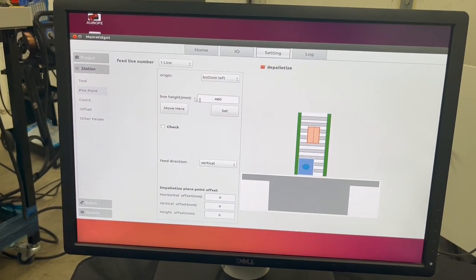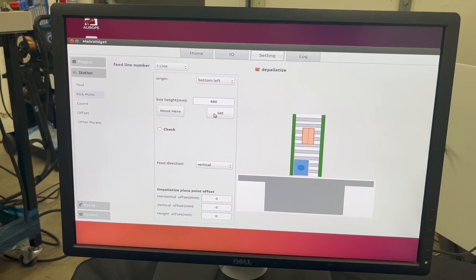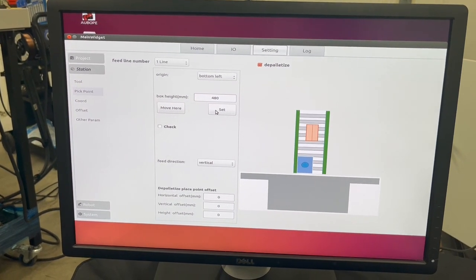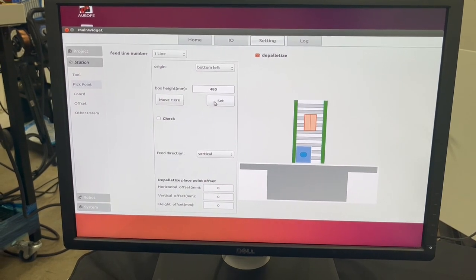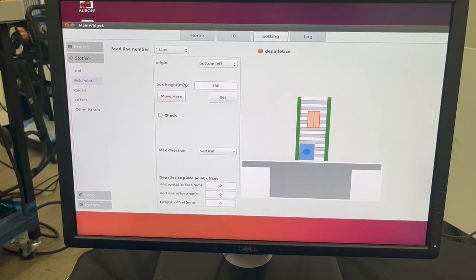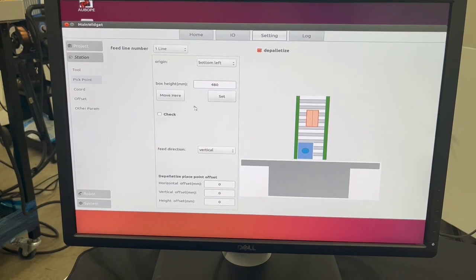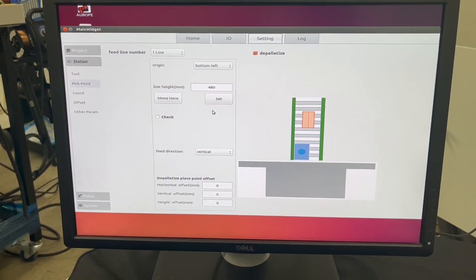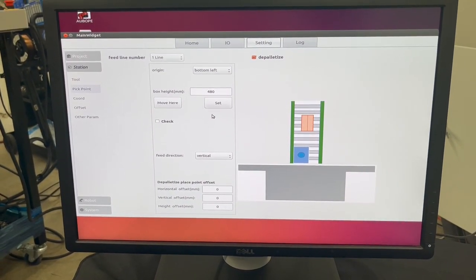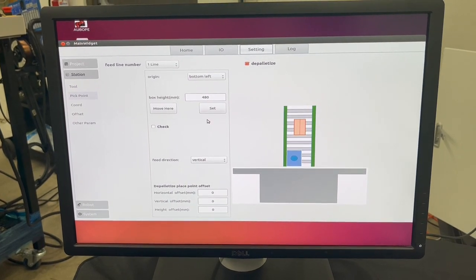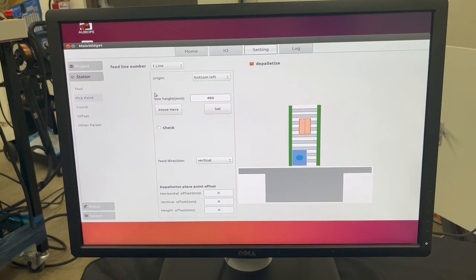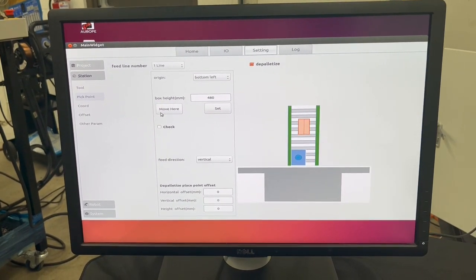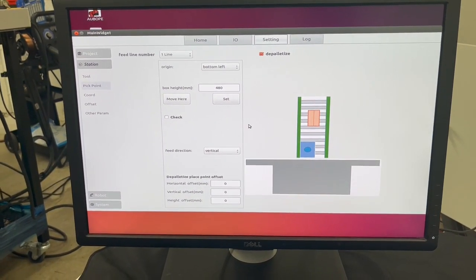This point is actually where it determines where the conveyor is, and the orientation of the conveyor, as well as the pick place of the box. You calibrate once, and if you change the product dimension on the same conveyor line, then you do not have to recalibrate this. If you calibrate once, the software will adjust its pick point based on your box sizes.